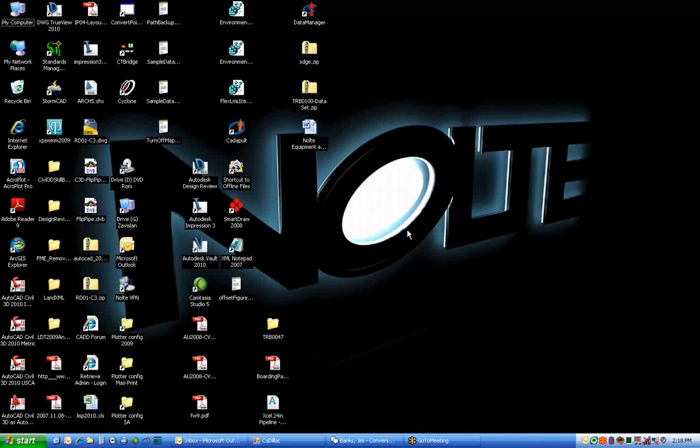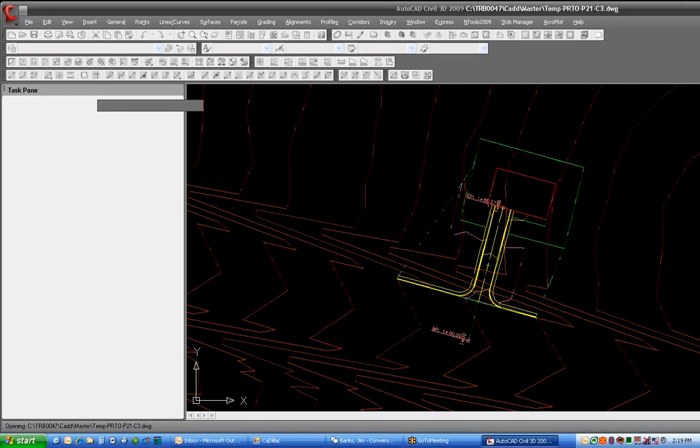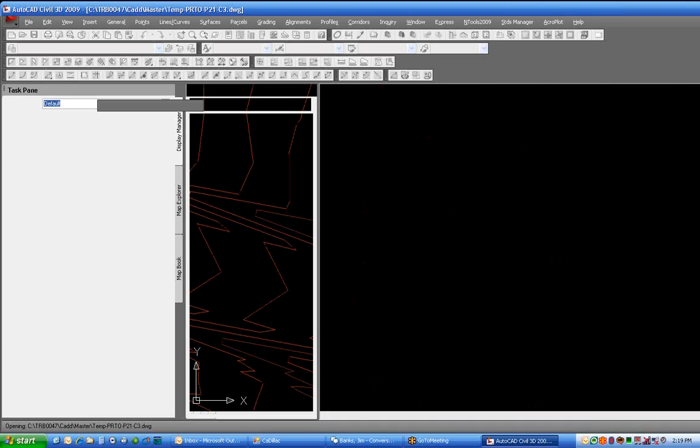That was a cool feature, so that is why I saved it. Okay. That was quite a fatal crash here. Let me reopen that. No warning whatsoever. All right, so now you know why I said save. Okay, that's why they weren't showing up. My grading group, grading object layer was frozen. And then when I went to save that, it did not like it. Or when I went to thaw it. So let me try it again once we come back in here.